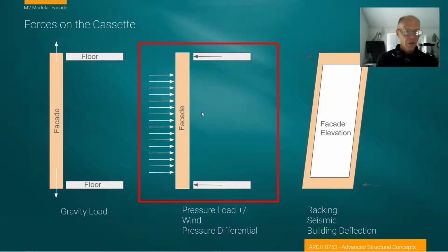So there's a lot of activity or actions that are working on our facade. We have two section views here and an elevation view. The red one is the one we're going to actually do some calculations on, but I want to make sure that we're clear that we're sitting in a constellation of issues about structure on the facade. So we have gravity loads on the facade, just the sheer weight of it having to be supported, just like any curtain wall would be supported, in the clips and the loads that would be applied with that.